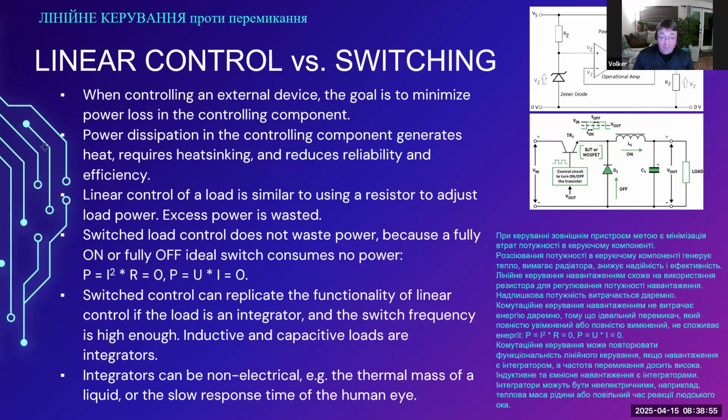And again, in this case, it doesn't matter how high the voltage is. If the current is zero, then the dissipated power is zero. So an ideal switch that is either fully on or fully off does not consume or waste any power.